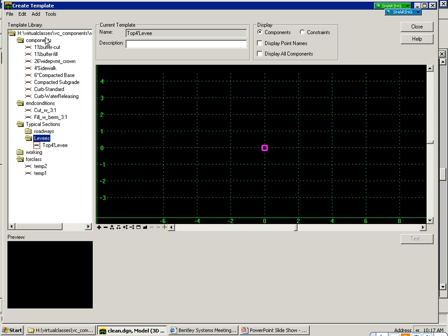Okay, what I'm gonna do on the components right now, so you do get the idea of the structure. I'm gonna go to components, I'm gonna right click, and I'm gonna say new, and I'm gonna say new template, and I'm gonna just say curb-1. So I've created this. Now if you notice, there's nothing here at the moment. I can put a description on it, and I can say this is for class training. So I'll do that, and so far I haven't done anything other than just create a template. I'm sorry, a component, no, a template. But in the template, I'm going to put a component.